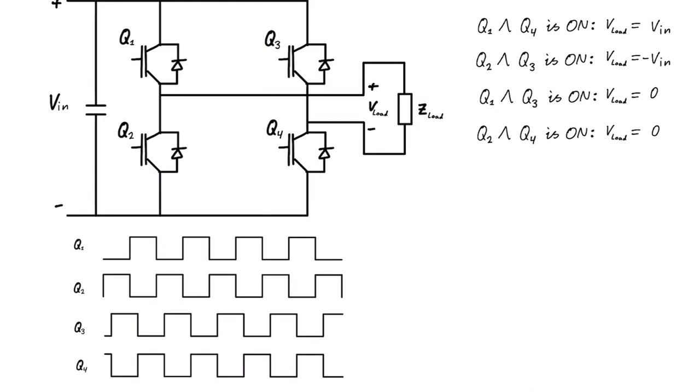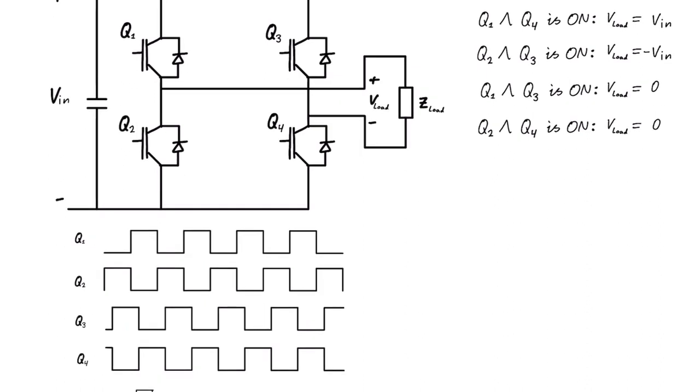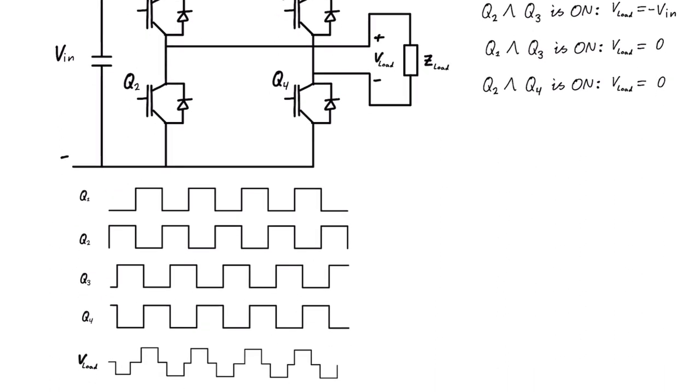And then if you see the pattern here, it will continue like this for the rest of the period, right? So the voltage should therefore end up looking like this. The current depends on the load, so what we want to do is V load divided by Z load. If the load is resistive, we get a waveform like this, just scaled, because a resistive load is constant.